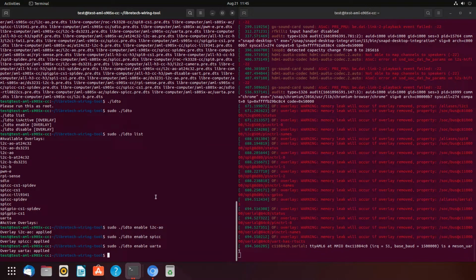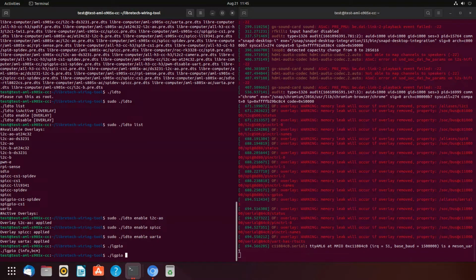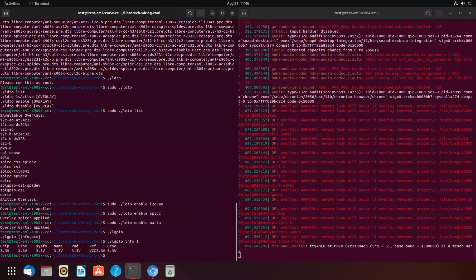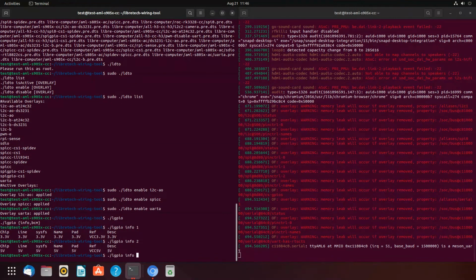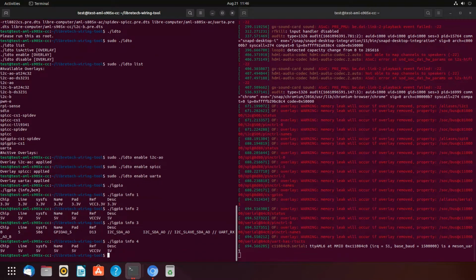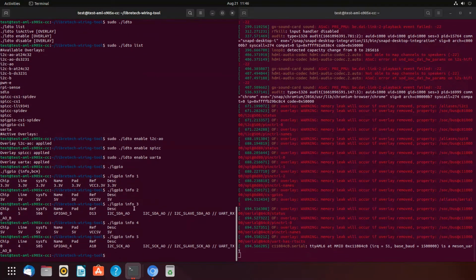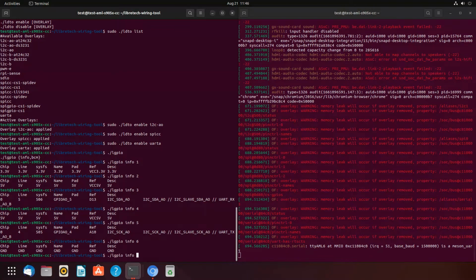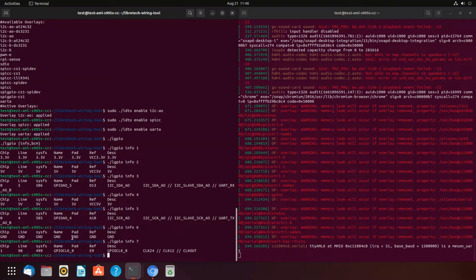Within our wiring library, we include the LGPIO utility for quickly looking up GPIO numbers. GPIO numbers can be in the form of the sysfs number, which is the legacy method, as well as the GPIOD numbers, which are based on the chip and the line number. Alternatively, it can also give the alternate function of the pin, such as I2C, SPI, etc.